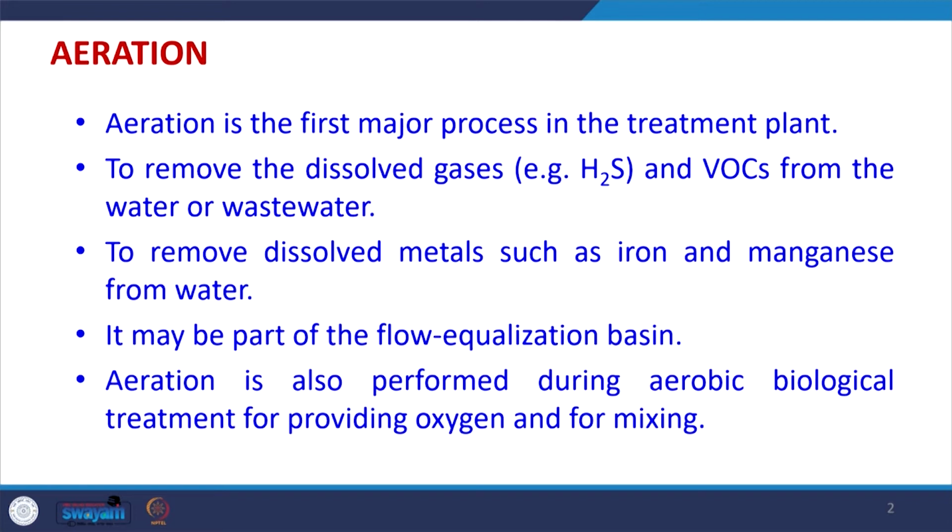As already told, this aeration unit may or may not be part of the flow equalization basin itself. Aeration is also within the treatment plant. Aeration is a must for any aerobic biological treatment process. So, aeration is always done in ASP, the activated sludge process, and some other processes as well.